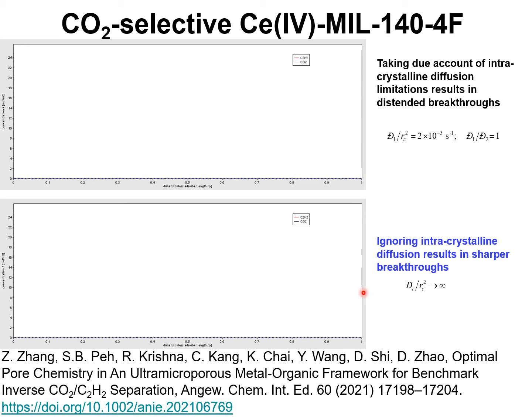Two types of simulations are compared, one in which diffusional resistances are duly accounted for, and the other type of simulation in which the diffusional effects are ignored, and we assume that the diffusivity divided by the square of the radius of the crystallite is very large, leading to practical equilibrium between a gas mixture and the particle of adsorbent at any position in the fixed bed.